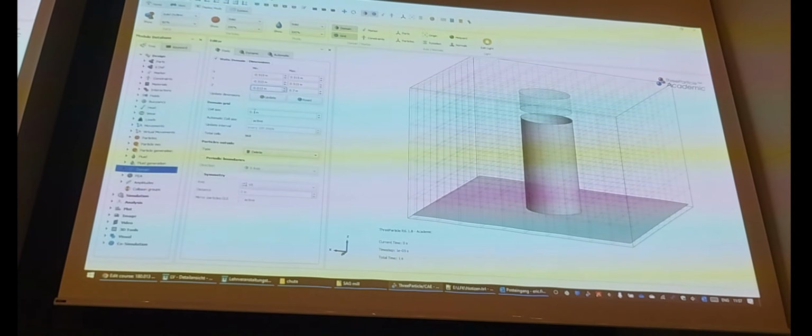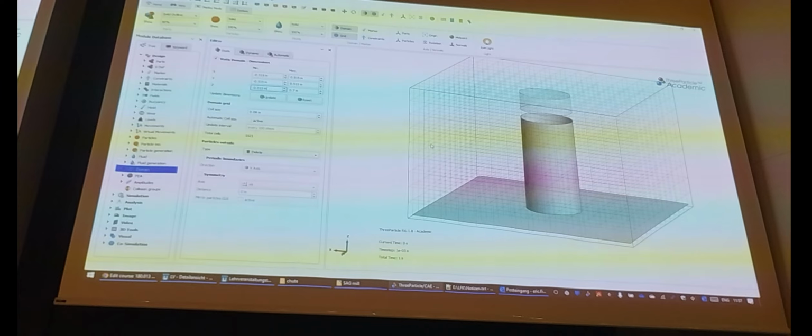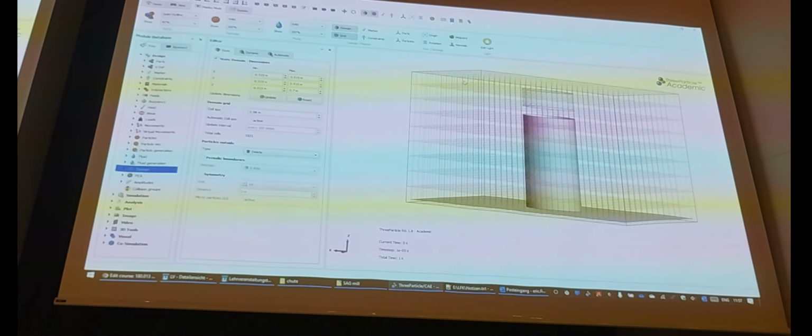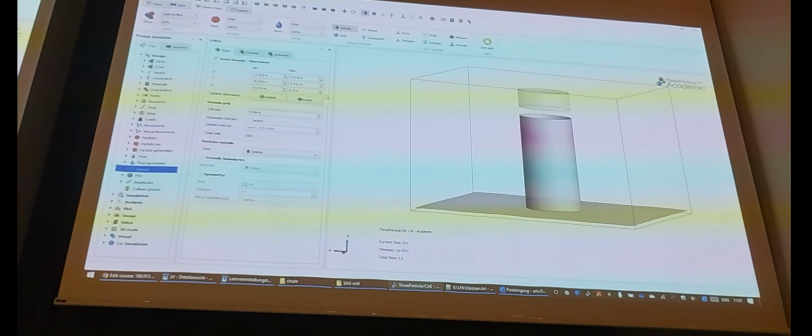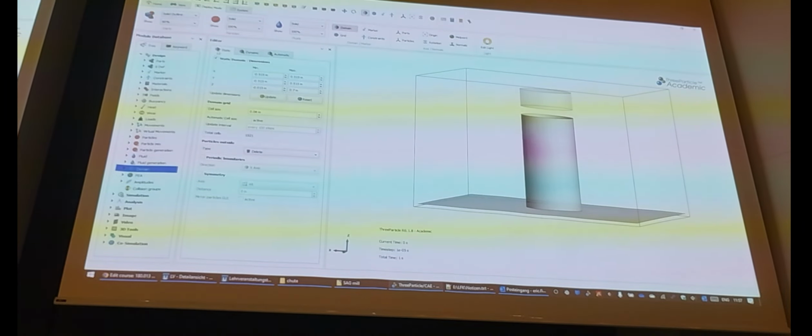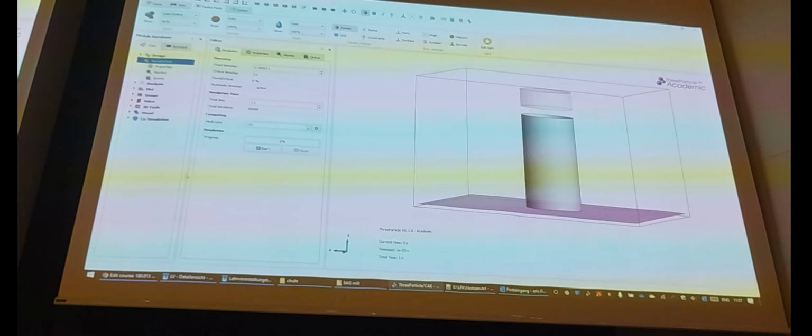I would stick with a value around the size of your particles, and I remember we have an outer diameter of 0.02, right? Something like that, or 5. So it's not that bad in that area. Probably a little bit smaller, something like that. A little bit more, because 1,000 is nothing. 1,500 still not that much. Let's see. But can we bring it off again? This one is important. So that all of our parts are inside of the domain. Otherwise, it won't work. Most likely. Save again. Go to simulation, and let's see if it's ready for run.